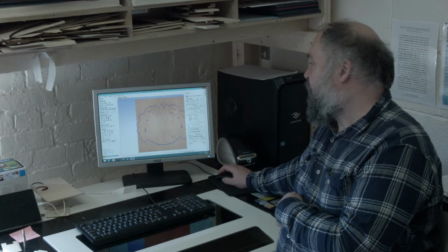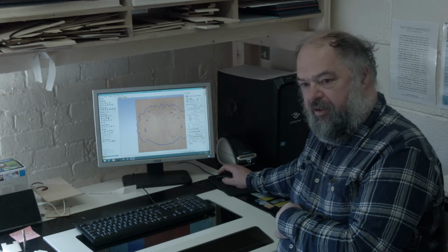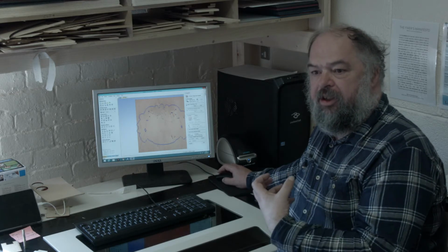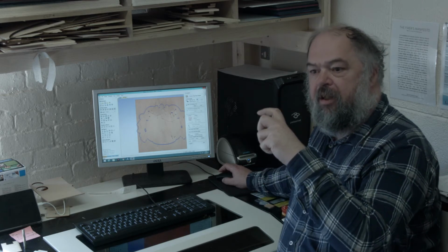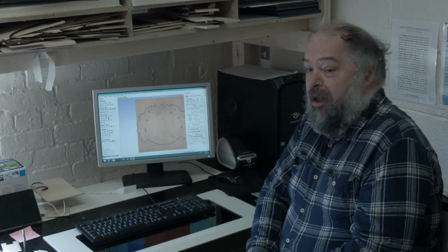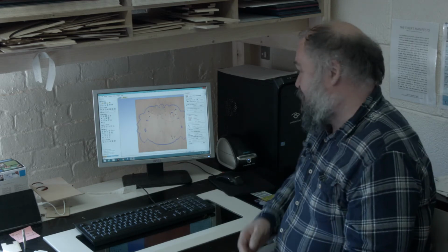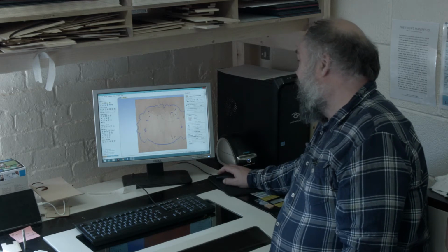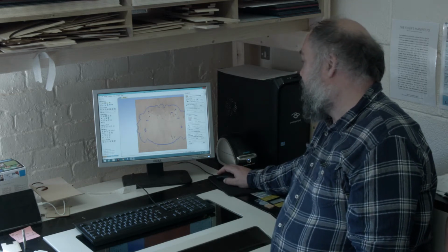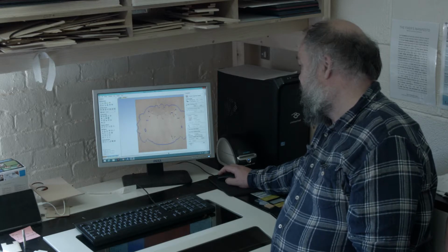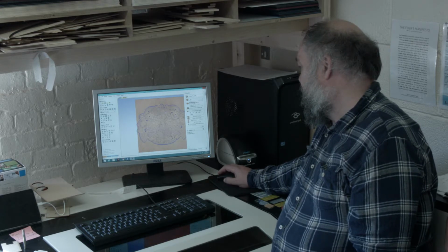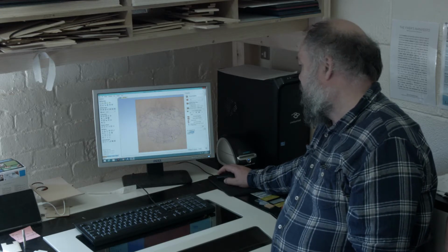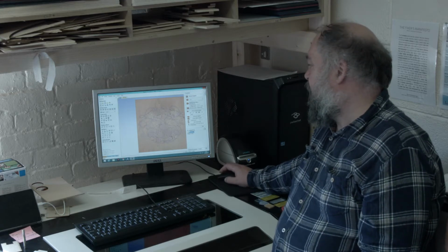You can also set in flat depth. What that is, if it goes beyond a certain depth with V-carve, if you have two lines which are very far apart, it'll carry on putting the V down at the angle, so it's at a 90-degree angle, and you can be cutting down for literally miles. So you can set it from there. Calculate. I don't want that one. So that created my V-carve path.